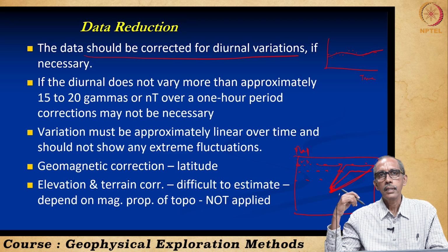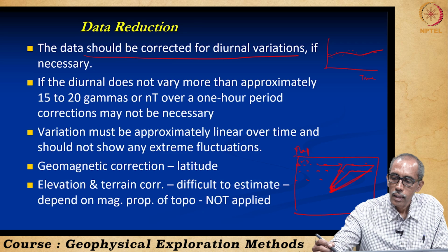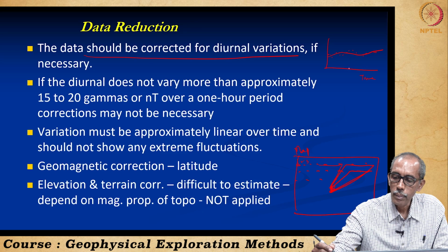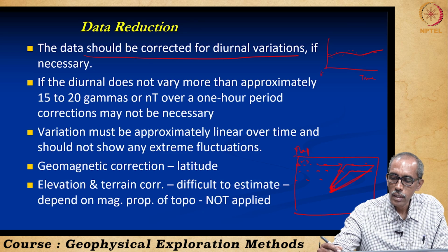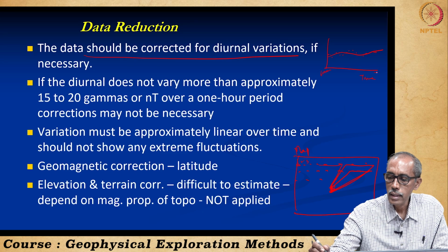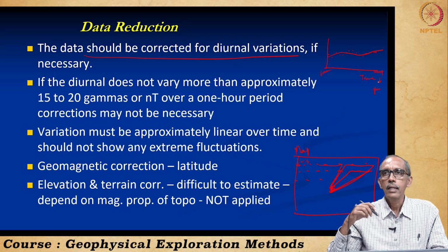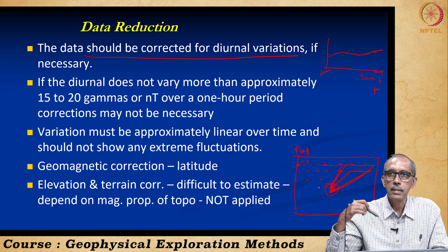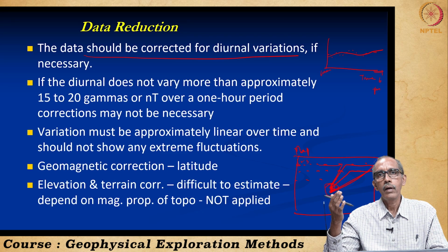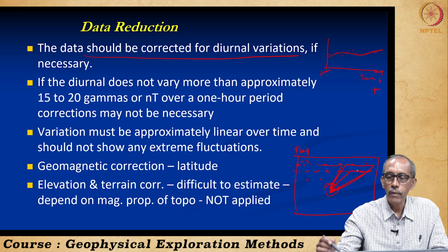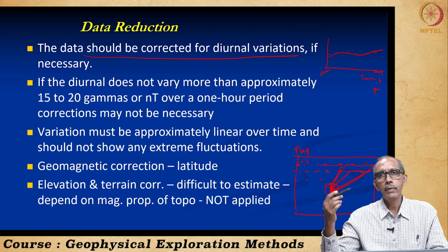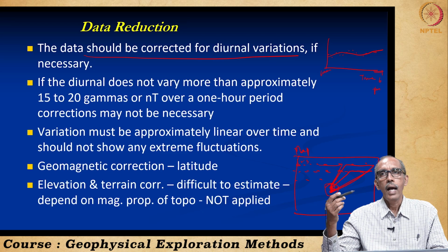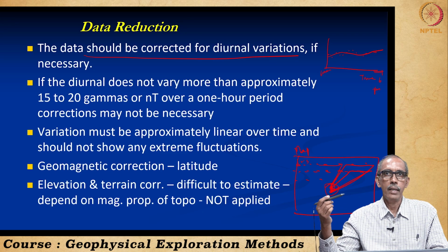So, why are we collecting this information? This diurnal correction needs to be applied to the magnetic data, right. Let us imagine we started our work at 6 a.m. and this is 6 p.m. Within a day there was some minor variation in the magnetic field intensity at the same place. The same will also be happening at all our magnetic stations. So, all our data has to be corrected as if they are taken at the same time.